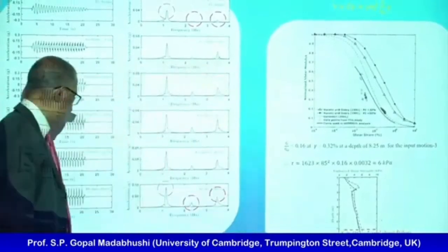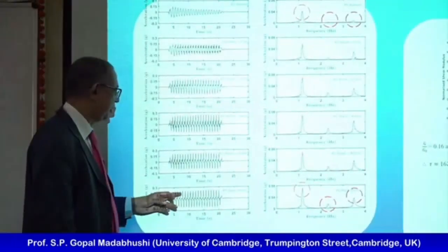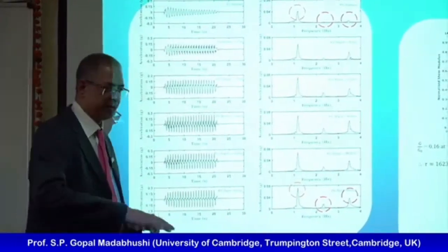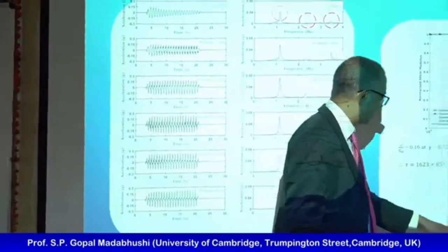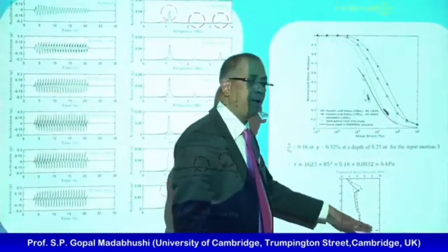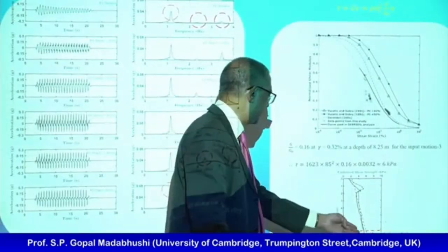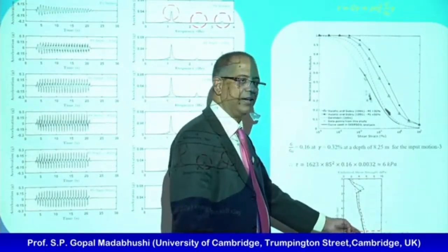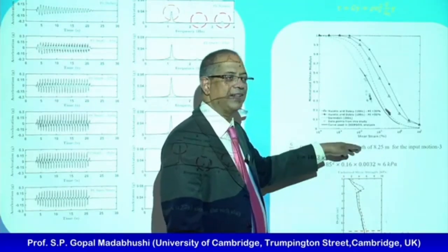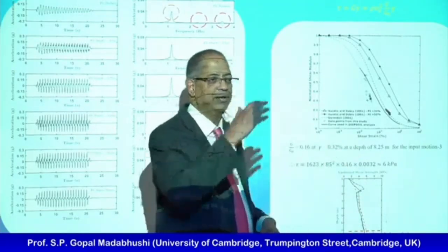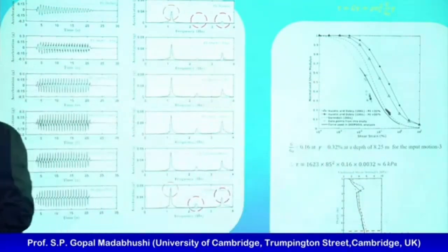So I'm applying here an earthquake that is nearly 0.25 G. Okay, very strong shaking. If I apply very strong shaking, the clay does not carry it above this level because its shear strength is only that there. If I exceed the shear stress, it is not going to carry that above that elevation. So it basically fails nicely there and protects your structure on the top.